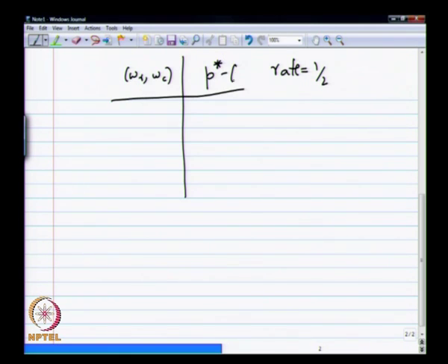This is P star for the Gallagher A decoder, or Gala decoder, which sounds like a better terminology. So I should say WC, WR, right? For some reason I always like saying WR, WC, I do not know why. Okay, so 3,6 is one choice which gives you a design rate of half, and that threshold happens to be 0.039 if you want to be very exact.